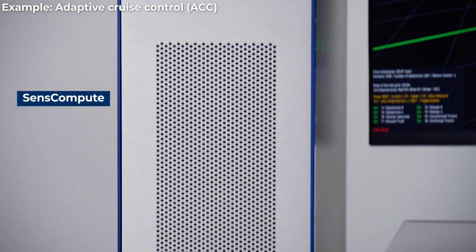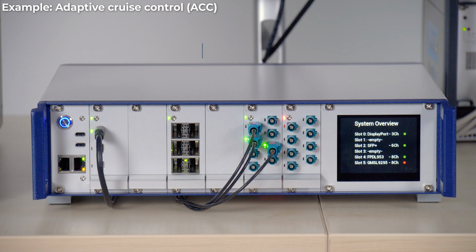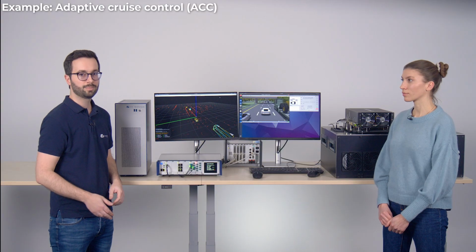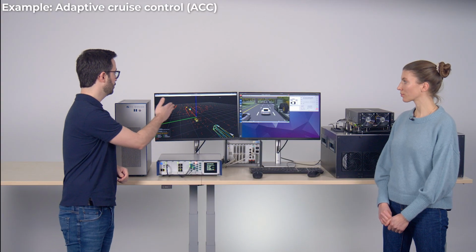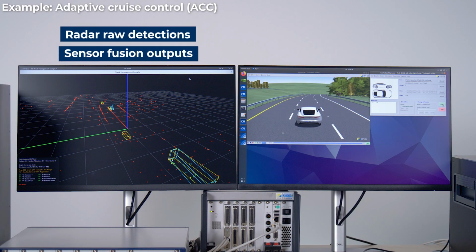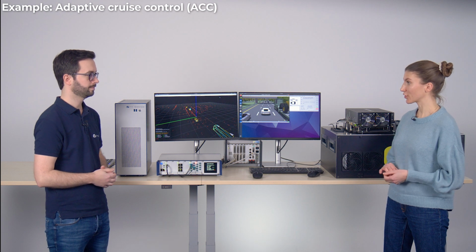Then the sense compute is calculating the radar raw signals, which are processed by our sense inject and injected into the system under test on the very right side. What's happening on the system under test is visualized on the second monitor, where we see the radar raw detections and also the outputs of the sensor fusion, so the tracked objects over time. Could you show us an example to see how it actually works?